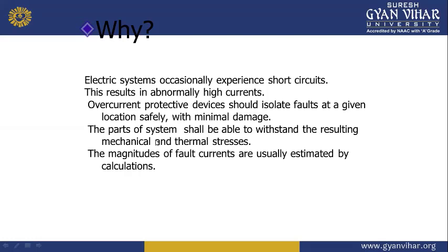The synchronous generator during the short circuit has a characteristic time varying behavior. In the event of short circuit, the flux per pole undergoes dynamic change with associated transients in the damper and field windings.